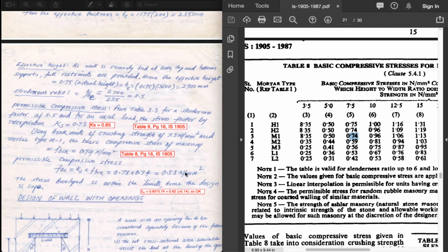Please ignore 0.58 over here. That is wrong because they have considered 0.78 as the stress reduction factor. So please ignore the written values of Ks and follow the annotated values given in red over here. So we get the permissible compressive stress as